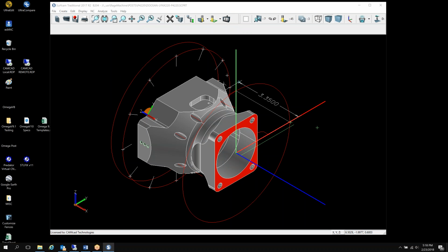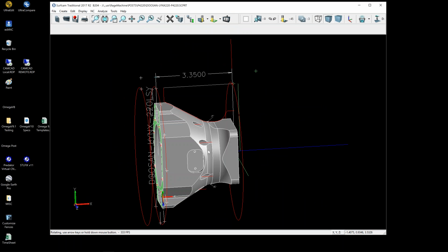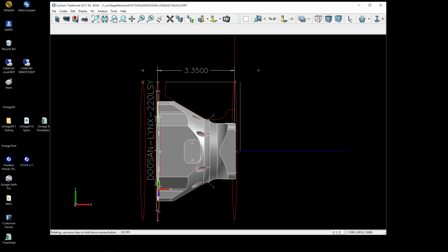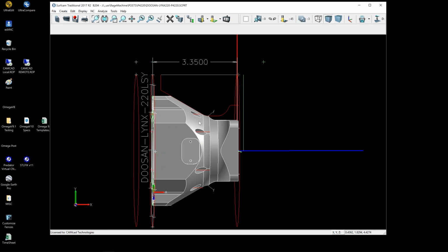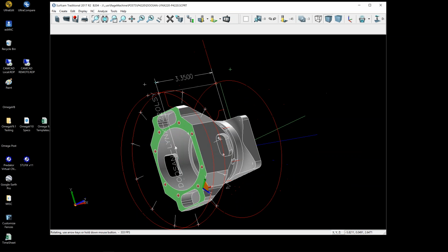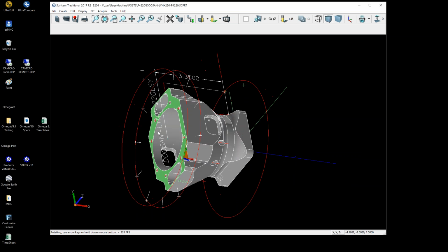So to recap, again, we use a machine datum, and that's critical. This allows you to program lathe type of tool paths in standard SurfCam mode. So we program for the front of the part here. We'd program over on the plus Y side over here for doing an ID bore if we were doing any turning on the sub-spindle and so forth.